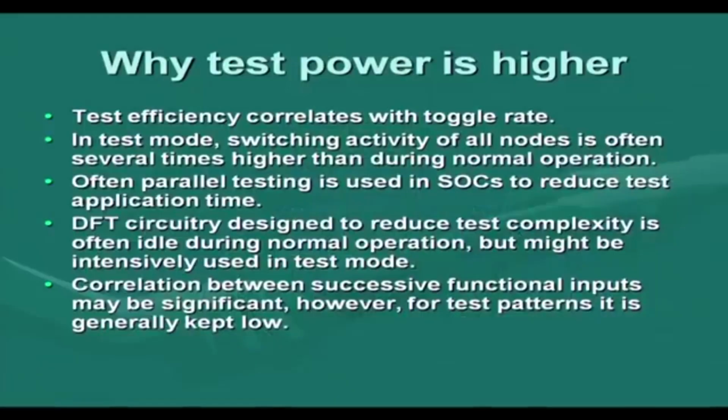Those modules are not active in the normal mode of operation, whereas in test mode they come into the picture. This circuitry will be activated in test mode. That will reduce the test complexity, but they will be intensively used during testing. So, the power consumption of those circuits will add to the overall system power consumption.